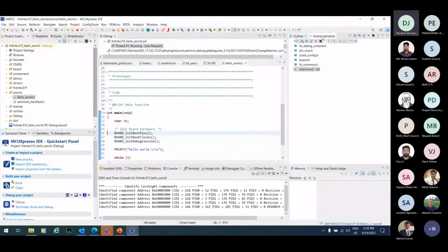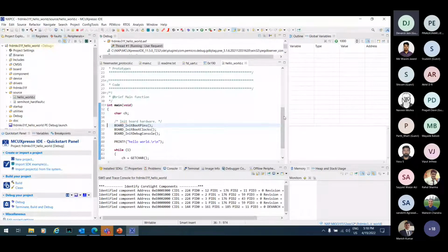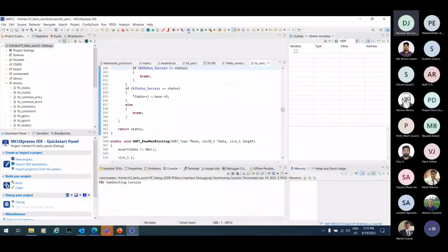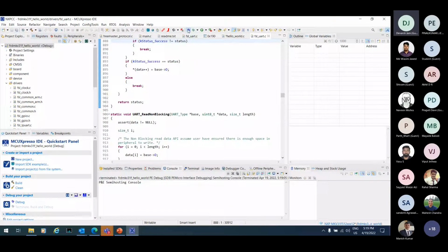And now there is a window where you can see the global variables in your software. There will be a lot of variables that you would like to see in the real-time debugging system. Whichever variable you define as a global variable in your system, you can look at it here. Let's say I define it as clock, okay, and then let's stop it, rebuild, and program again.